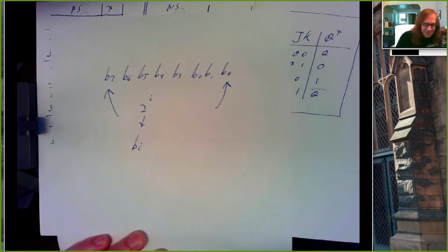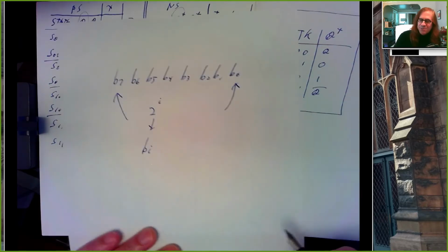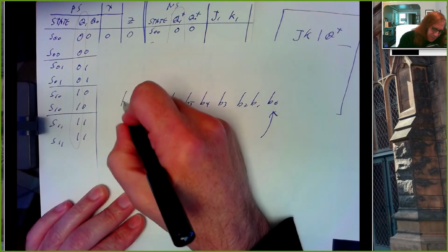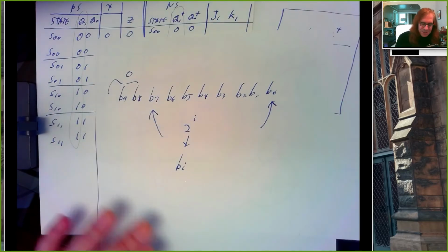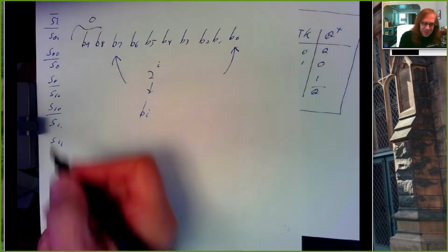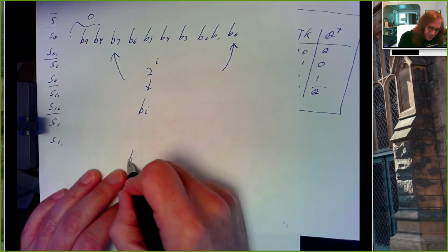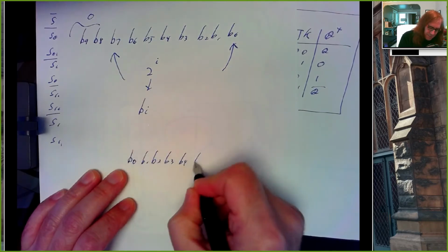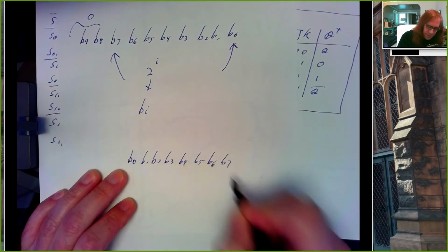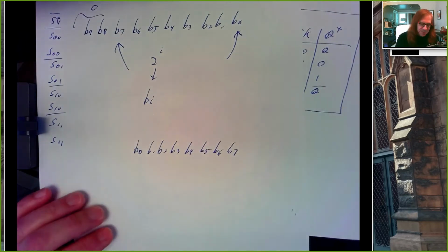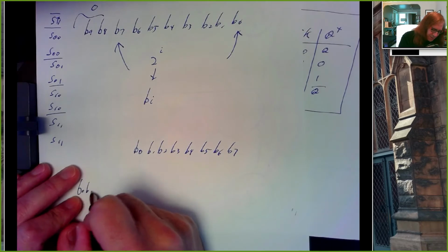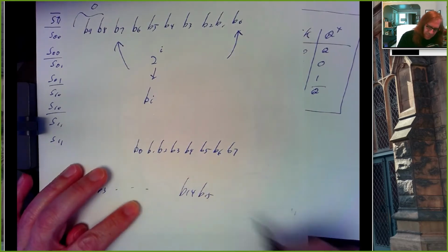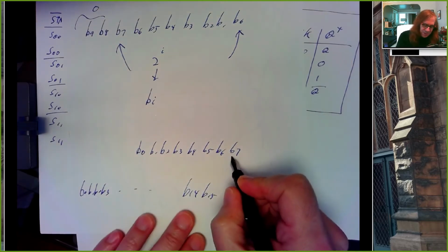And if we have an 8-bit number and we want to treat it as a 16-bit number, we simply add on more bits and make all of those 0. Now, if we numbered in the other way, and then we tried to put this in a 16-bit number, which looked like this, bit 7 would no longer be bit 7.